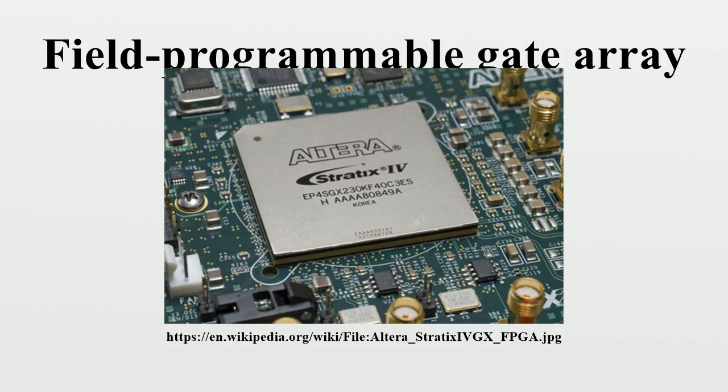FPGAs that store their configuration internally in non-volatile flash memory, such as Microsemi's ProASIC3 or Lattice's XP2 programmable devices, do not expose the bitstream and do not need encryption. In addition, flash memory for a lookup table provides single event upset protection for space applications.